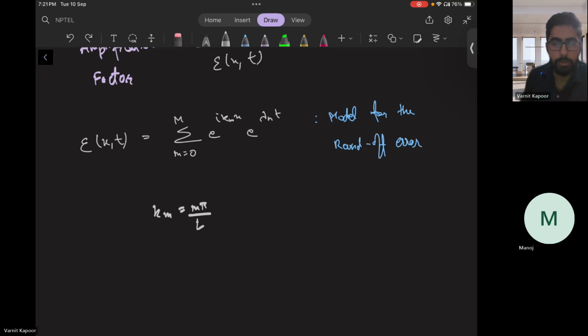Right. So now, is this equation linear or non-linear? It's a linear equation. Any non-linearity of the source term or diffusion you would circumvent by introducing additional iterations. But the resulting equation which you always get is a linear equation in the form Ax equals B. All the PDEs, once solved, turn into a linear equation. So we are solving for epsilon, the error.